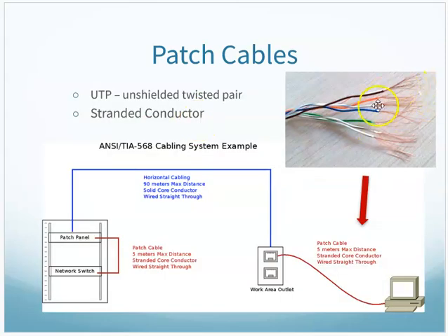That patch cable is typically stranded conductor, unshielded twisted pair cabling, stranded conductor for flexibility purposes. So this cable here is usually stranded core, so the cable can bend a whole bunch without breaking.